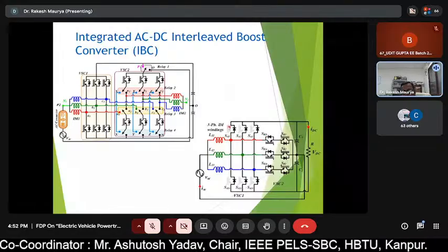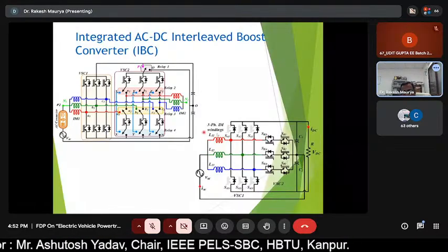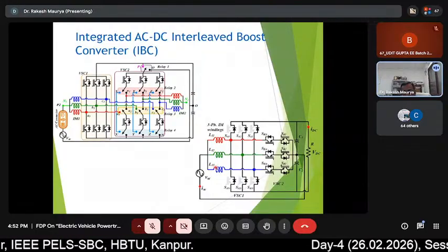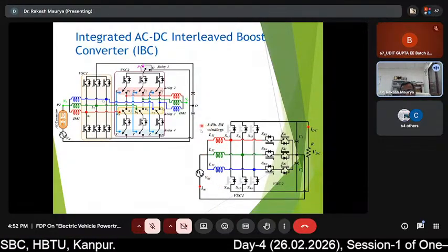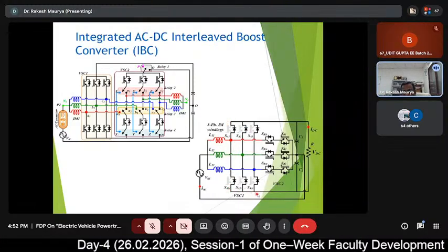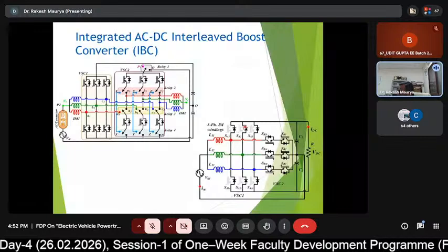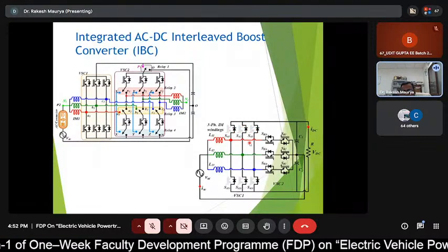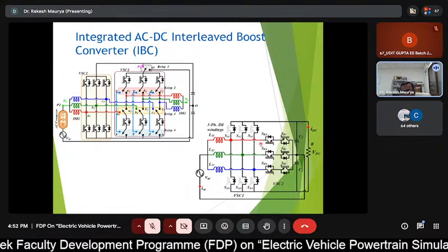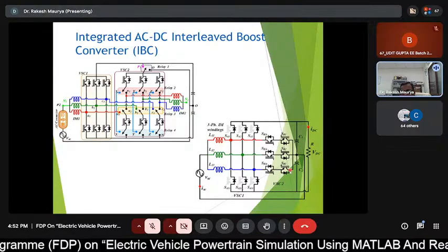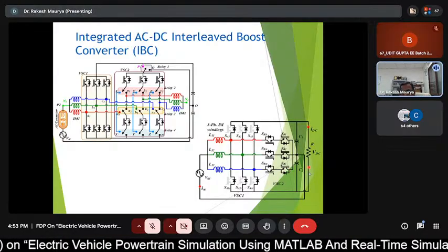So this is the configuration we made, where L11, L12 and L13 are part of the induction motor winding. And obviously, for the one VSC, if we are not giving any pulse, it will act as a diode rectifier. So this is the three-phase diode rectifier. And the second VSC you have to configure as a Vienna rectifier topology. So the DC link is available here.